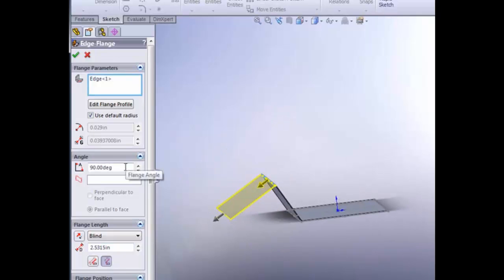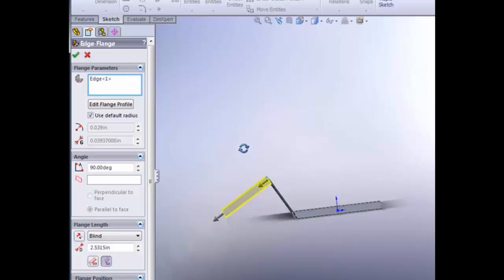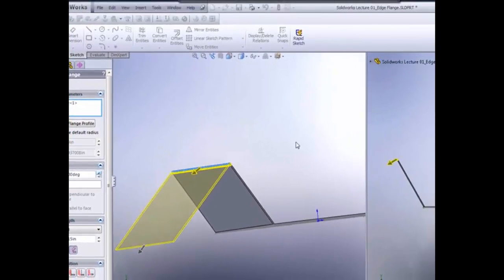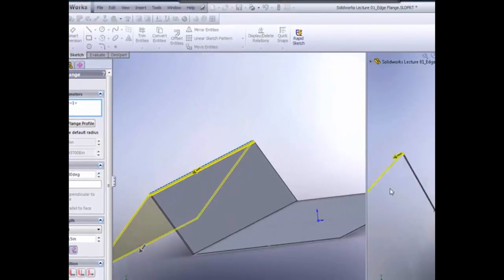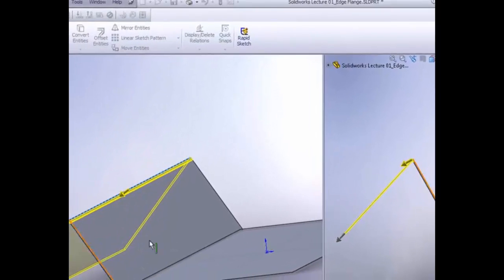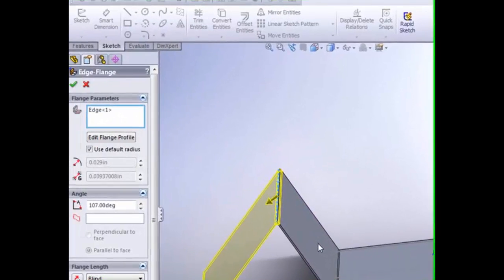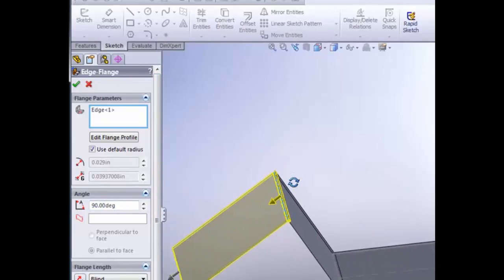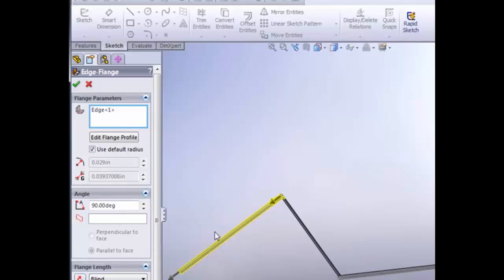And let's say right now it's at 90 degrees to this material here. We can't go less than 90, we can't go more than 90, right? Because otherwise we're getting an interior angle that is less than 90, which is not allowable. Our brake can't do that, actually. It has to be at least 90. So 90 degrees. Let's say this is also going to be at 30 degrees.